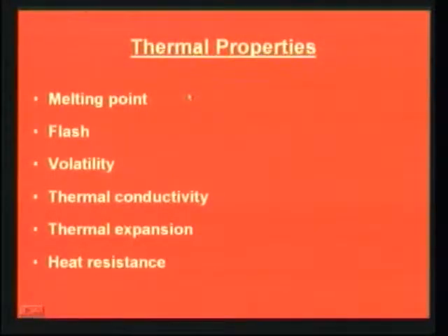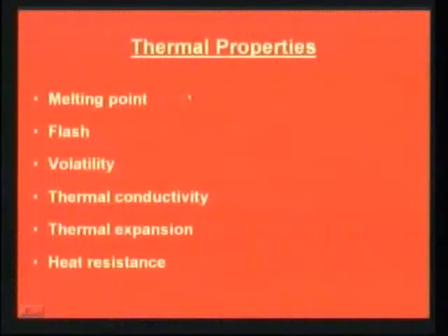The next thermal property is flash point. This is an important factor when selecting oils for transformers, switch gears and other oil immersed apparatus. An insulating material should not catch fire at the operating temperature. The flash point of a liquid dielectric is that temperature at which the liquid begins to ignite.